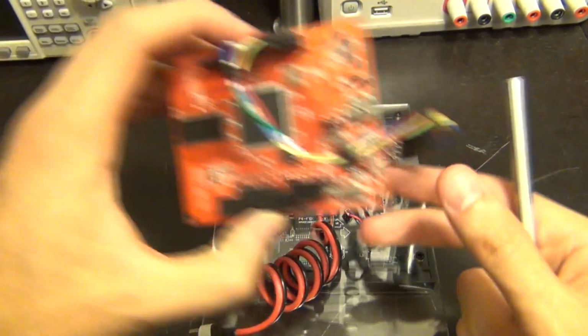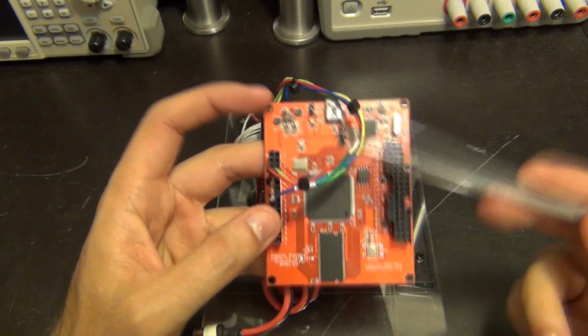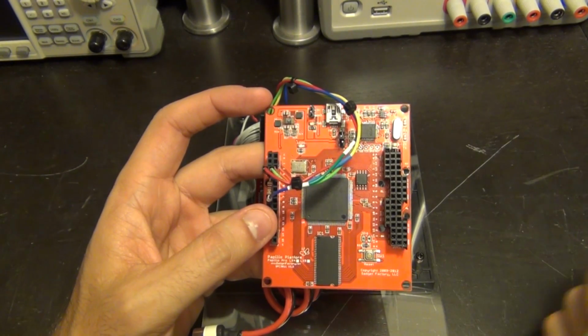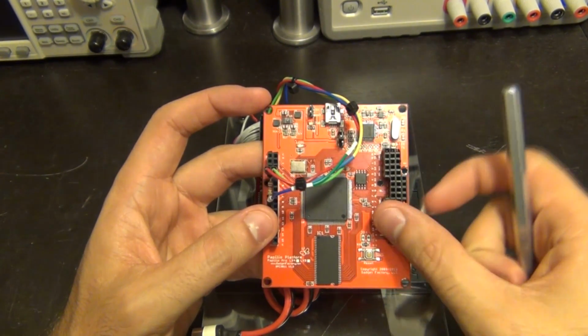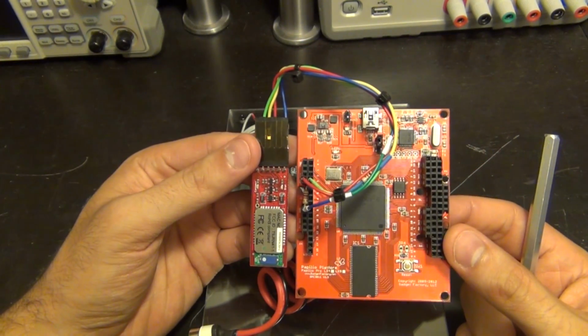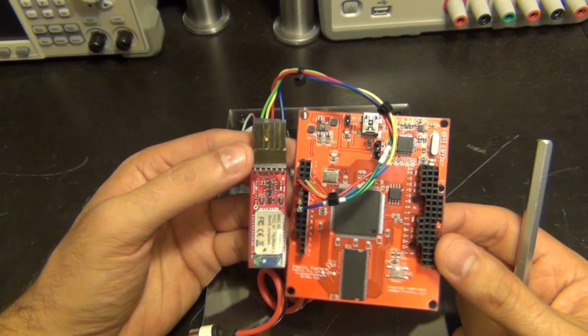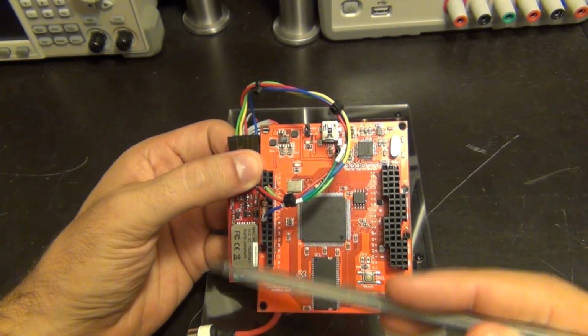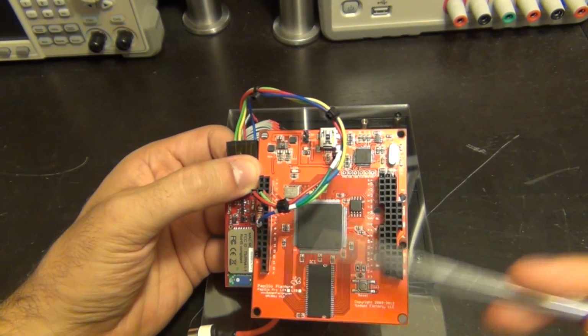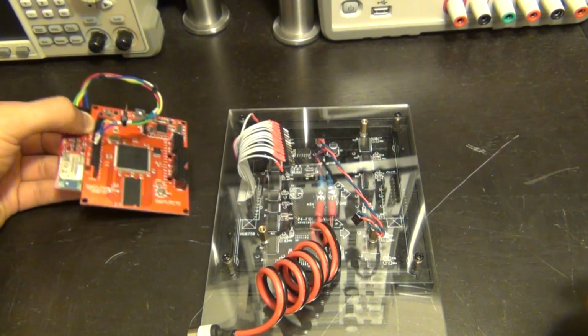And our FPGA board is this FPGA board right here. It has a Spartan-6 on it. Of course, it doesn't matter what FPGA board you're using, because the logic, the algorithm is of course going to be all the same. And I'm using a simple Bluetooth RS-232 interface in there so that we can send our frames with RS-232 directly into the FPGA. So Bluetooth serial data comes in, goes into the FPGA. FPGA does this thing that we're going to explain, and it's going to generate the waveforms necessary to drive the display.